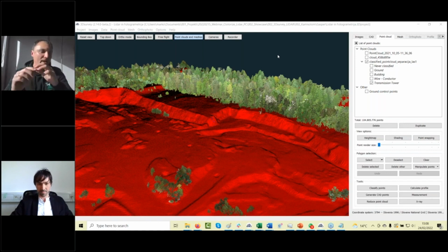Exactly. And what I would say is that the Mavic Mini has the best opportunity for photogrammetry. Why? Because the Mavic Mini doesn't have autofocus. It has a stable focal length. In this case, as soon as you calibrate the camera of the Mavic Mini, you will achieve very good accuracy, and you don't even need to calibrate the camera. Just add a precise focal length. It was tested 2 years ago, and it achieved very good accuracy. It's not so well estimated on the market right now, but it has very, very good accuracy, especially for small-size surveys, like buildings or small land plots.